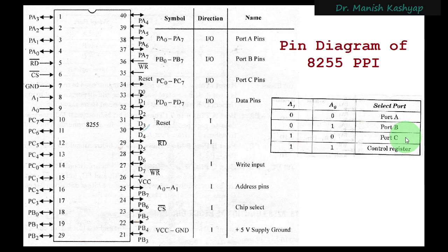That is how you can interface your devices. Some older devices which had only 4-bit connections can be used with the upper or lower part of port C, right? It's not that if you have formed groups, you can take 12-bit data combinedly. That's not what I am saying. I am just saying that they are grouped. And what is the advantage of that group? We are going to see it soon. Now, since 8255 is programmable, we have a control register also, right?